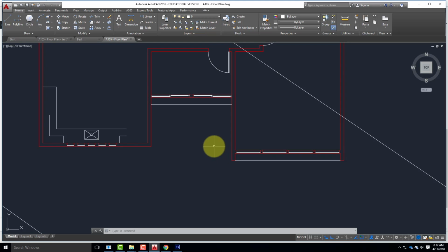Changing the color in that category and not at the end doesn't affect when you print it out, though? So right now, these lines would print red because I've changed the color to red. So before I print, I'm going to have to go back and change them back to white. Unless you do a monochrome line table. Yes, you could theoretically do a monochrome line table, and it would work. I generally don't do that, but you could if you wanted to.